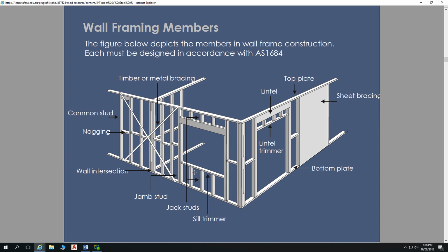So you just plug in the information and it specifies lintels for you. And that's typically what I've done, rather than work through the timber framing code to determine lintel sizes using natural pieces of timber. I've just used a program like Design IT that spits out the lintel sizes. You get a report that details the information you put in there and the selected pieces of timber and what those pieces of timber will have the capacity to support. And that report can then be included with all your other design information. So I find those programs very handy for calculating lintels.